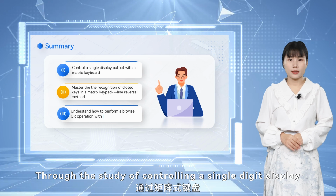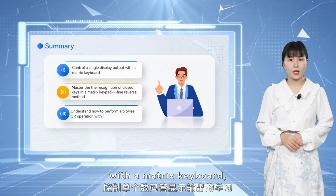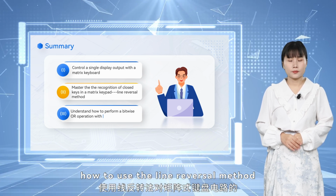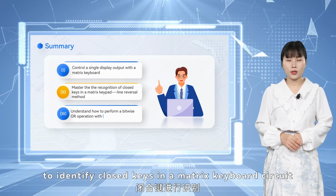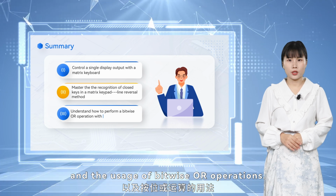Through the study of controlling a single-digit display with a matrix keyboard, you should now understand how to use the line reversal method to identify closed keys in a matrix keyboard circuit and the usage of bitwise OR operations.